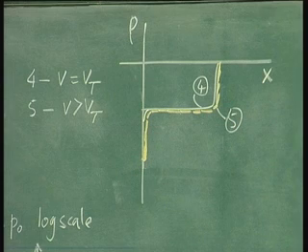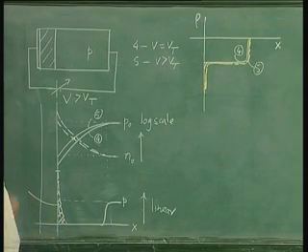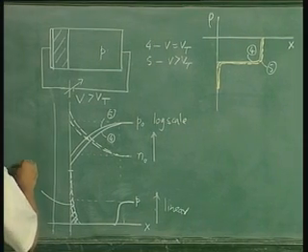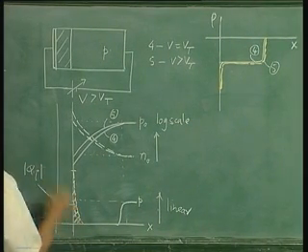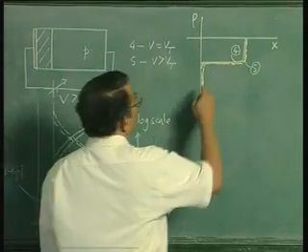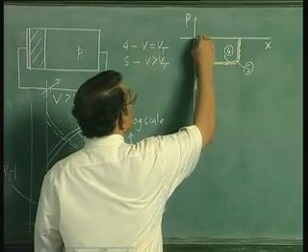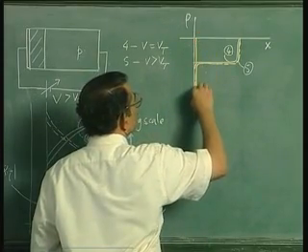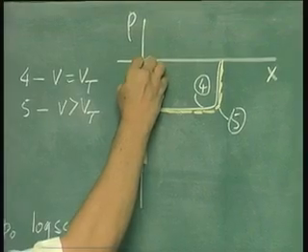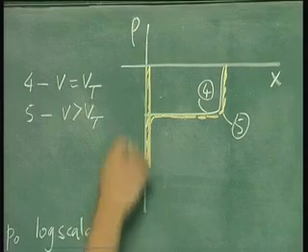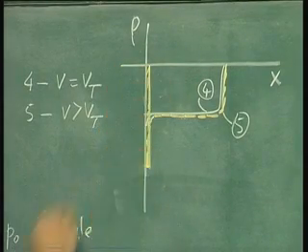What we will do is call this area under the electrons, or the electron charge, the inversion charge, and denote it by the symbol Qi. Now the charge of electrons is negative, so we will put a modulus here because this area is positive. Similarly, here we will show the space charge because of electrons by a separate delta function. This is like a delta function, that is, it is showing the electrons as a sheet of charge.